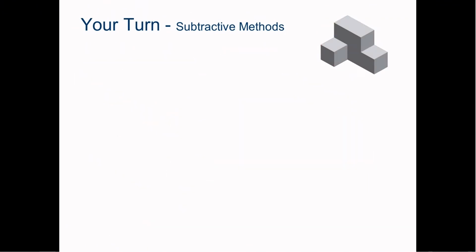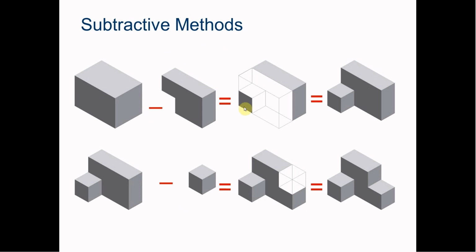All right, let's go back again. Remember, we need to remove this shape. We could draw line, line, line, line, line, line, or draw a rectangle here and another rectangle here and delete the material in between, the line in between them. But if we just quickly draw this rectangle and then tell it to choose all the other material that's not that rectangle, we'll accomplish our goal and it'll be faster.